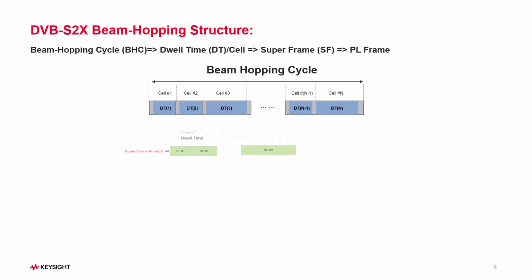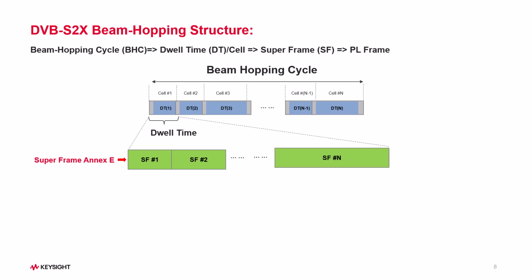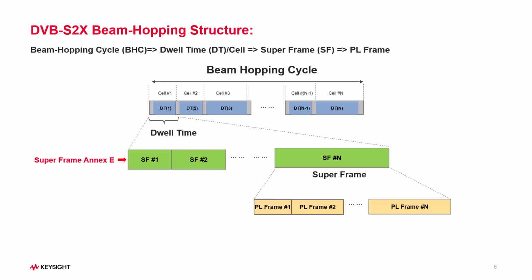You can stack multiple superframes, each with different size. Each superframe bundles multiple PL frames, and each PL frame can have different lengths. You can even mix time slicing inside beam hopping for maximum flexibility.